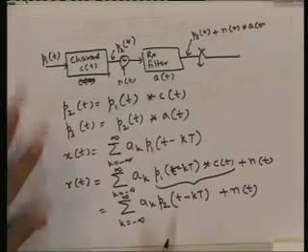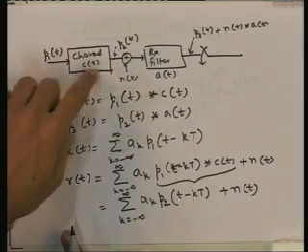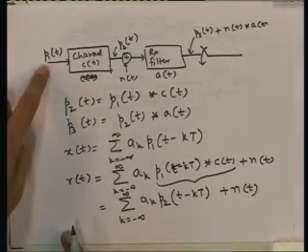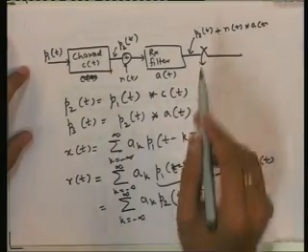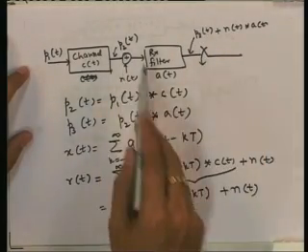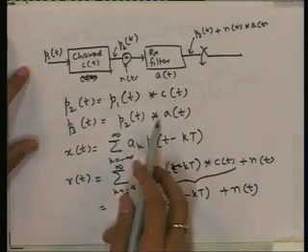So what have we done here? We assume that p2(t) is the convolution of p1(t) and c(t), that is, p2(t) is the output when you give p1(t) as input to the channel, and similarly p3(t) is the output when you give p2(t) as input to the receive filter a(t). So p3(t) is the convolution of p2(t) and a(t).